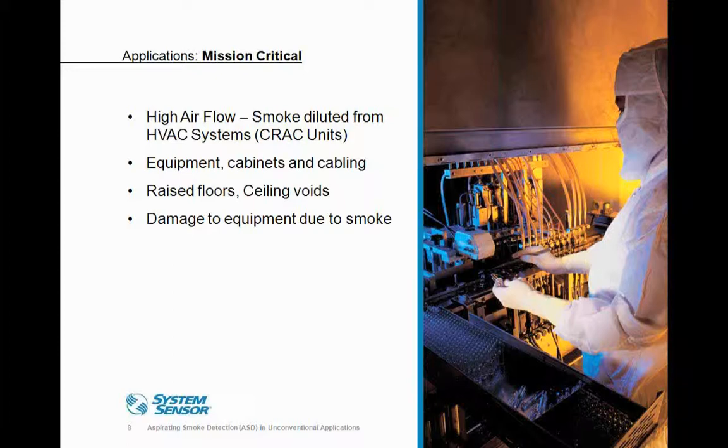Due to the concentration of cabling, cabinets, and high heat equipment, the possibility of smoke and fire can certainly be heightened in these environments. Because of this environment, it's necessary to put smoke detection in several places throughout a server room, depending on its layout.